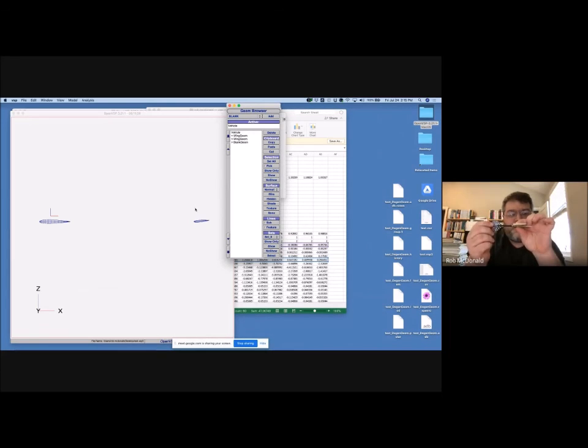But I've still got the tail back here in the back to keep the nose pointing forward, to keep it stable, right? So that's how a normal airplane works. Now, there's plenty of subtlety. If I didn't have this tail at all, and I just had this wing, I would have that lift, but when I increase the lift, the moment, depending on exactly where the CG is, would either stay the same or it would actually increase. And so when I get that perturbation, when I hit a little bit of wind, it would then tumble, right? It would just keep going.